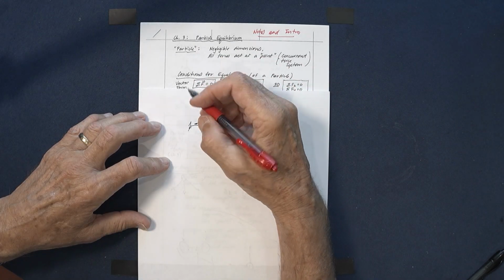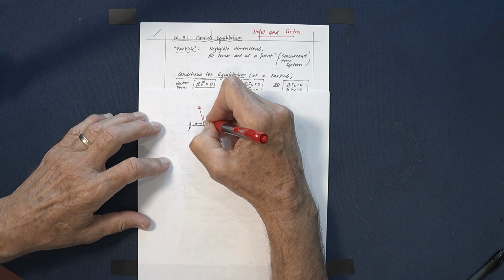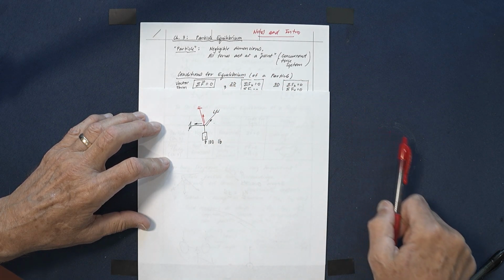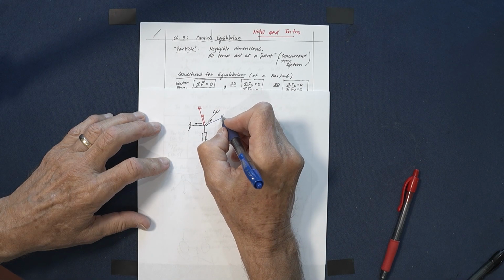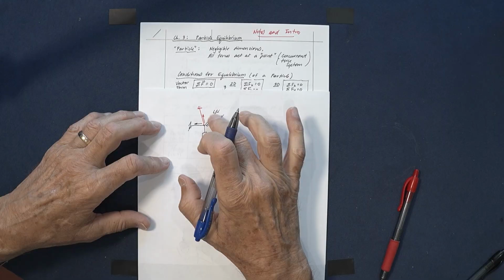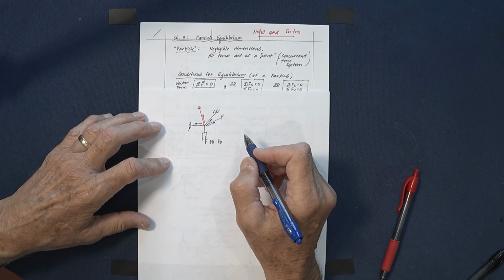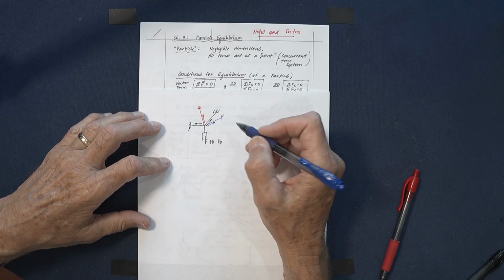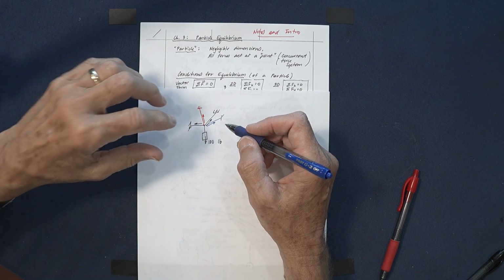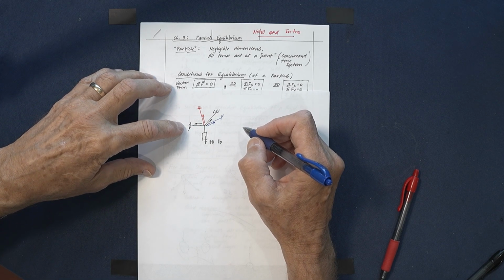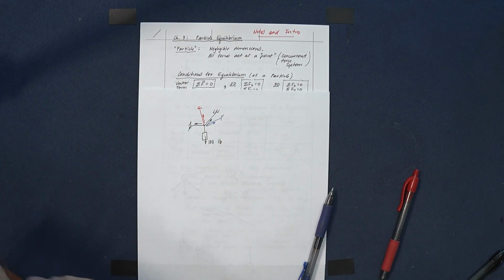But if there is a third cable here with a third force, or maybe a fourth cable with another force, now I have 4 unknowns. And if I sum forces in the x and y, I just have 2 equations. And I'm in trouble. This problem with more cables than 2 is statically indeterminate, whereas if it's just 2 cables matching my 2 equations, it's statically determinate.